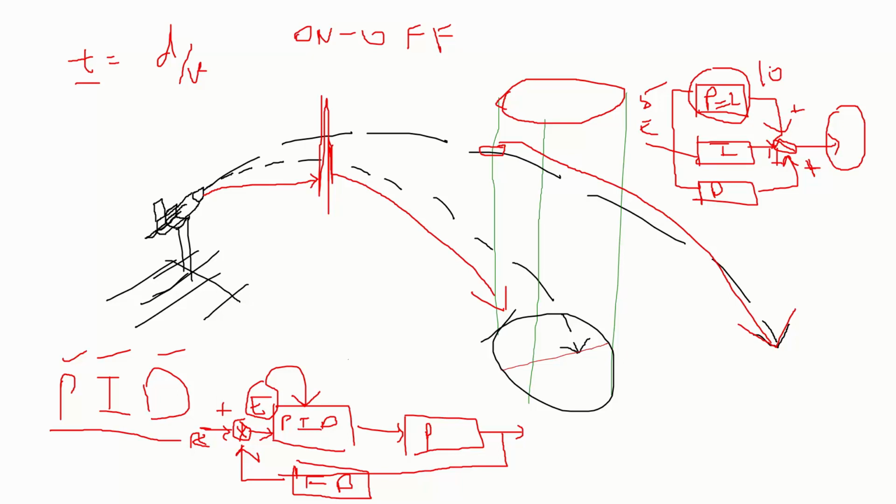Now, the integral controller keeps on integrating the error signal over a time period. That depends upon a scaling factor as well, called Ki. So you'll have Ki in the integral controller, the scale factor associated with it, and you're going to integrate the error signal.